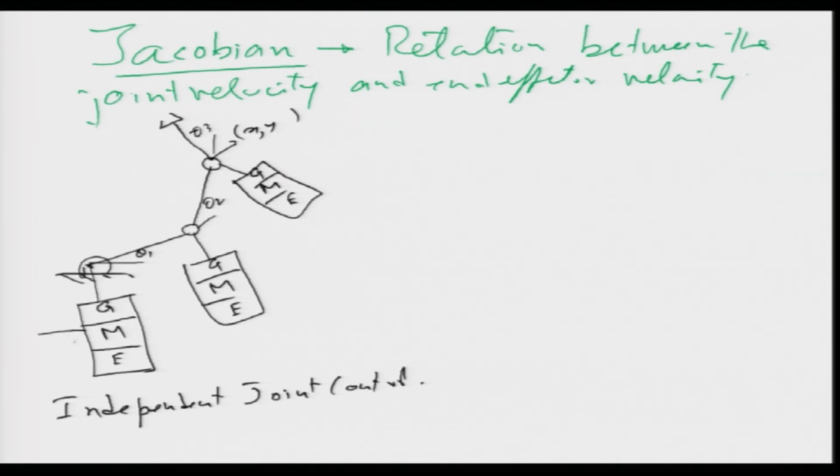If you want to move the end effector, say I want to move from here to here, how is it going to move? Essentially, inverse kinematics will tell me that at this position and orientation, what is the new theta1 dash. Then it will do theta1 dash minus theta1. So by using inverse kinematics I find the difference between theta1 dash and theta1 and make that into an error of theta1.